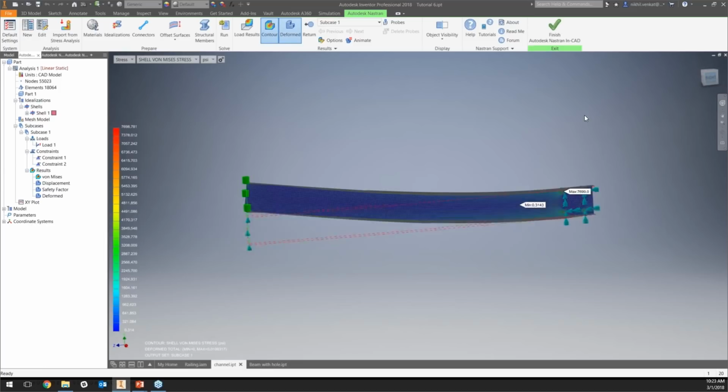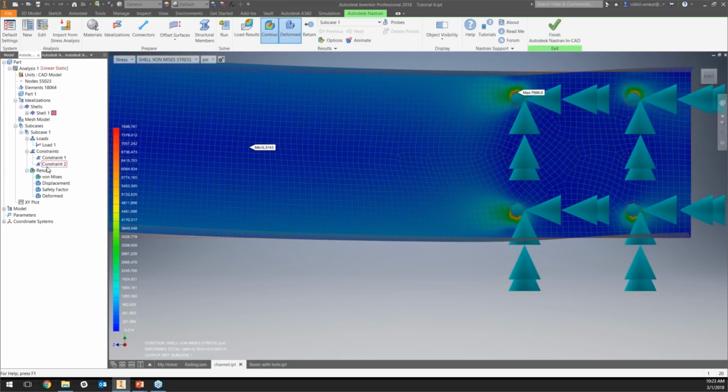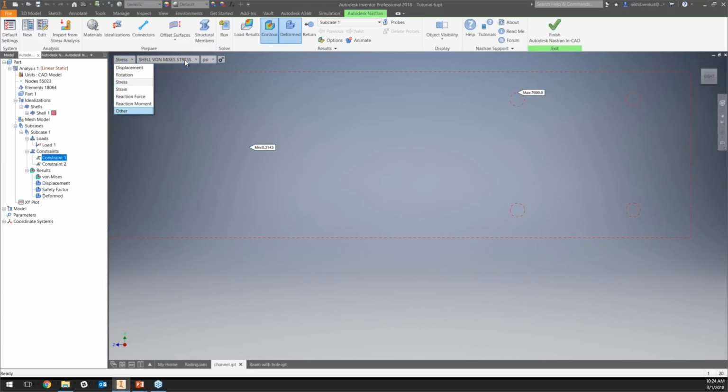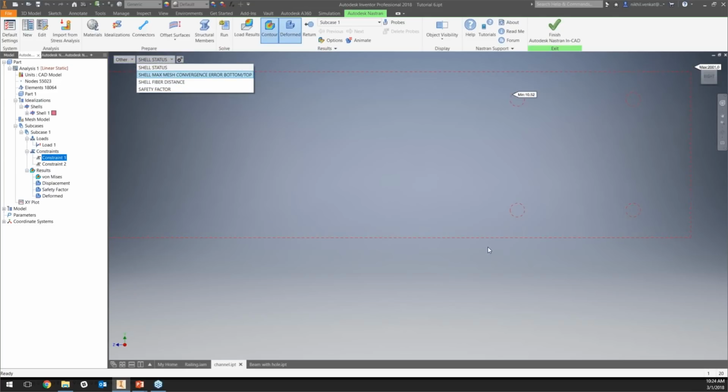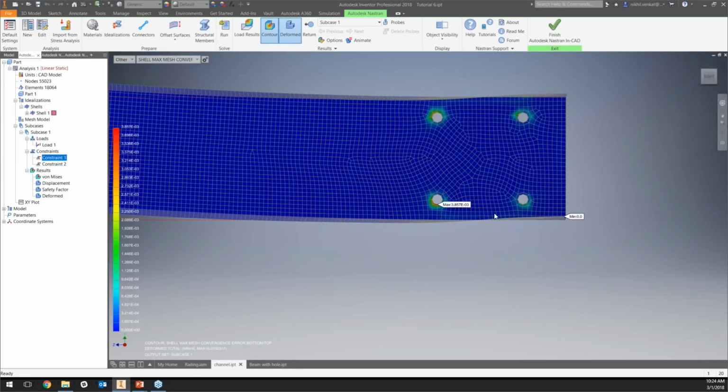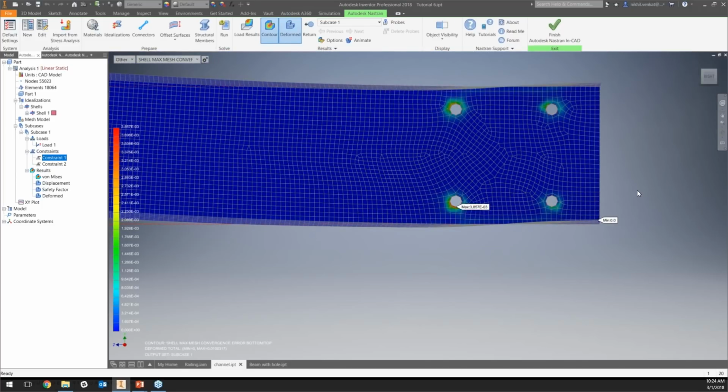Now, one other thing that I wanted to show you here is, let me just make these invisible, the mesh convergence factor. We know this is a good mesh because if you look at the mesh convergence error, the maximum error here is about 0.4%. So that's okay for a solution error. This is your preliminary way to verify and validate your results from a simulation: you look at the mesh and see if there's anything you can do to actually improve the accuracy of those solutions.